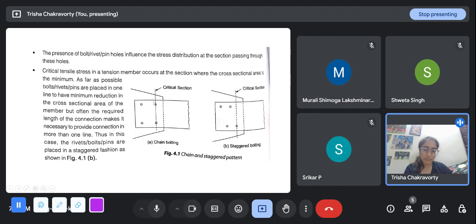See, when the tension is applied in this direction, the critical sections that we have to consider are perpendicular to the direction of the tension, right? The tension is applied like this, so this cross section is this plane cross section. If the tension is applied along the x axis, then we have to look at the cross section in the yz plane. So here is my yz plane, this dimension, and the one going into the plane.